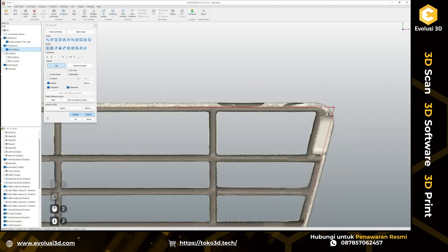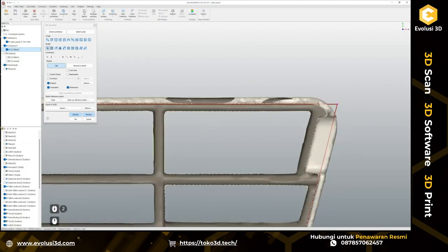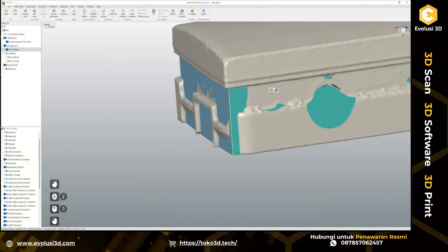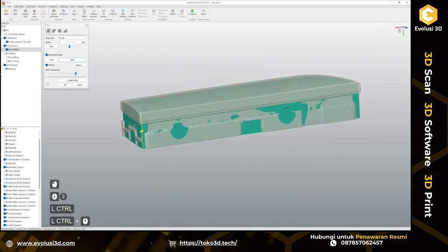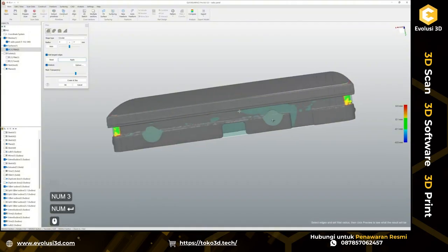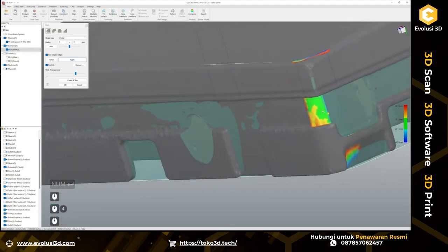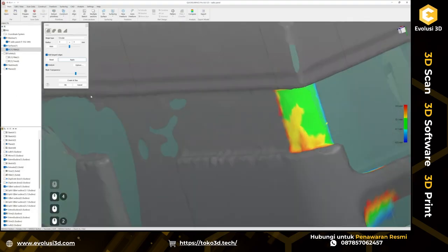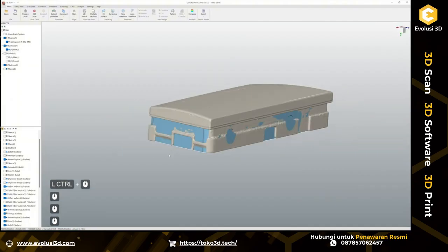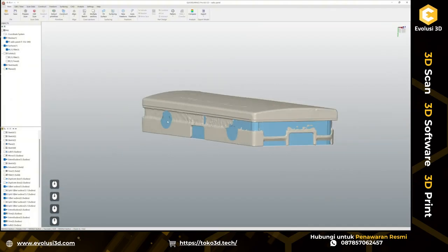Well, to be honest, since this corner is being cut away later, probably this might fit as a normal fillet as well. So let's try to add here a fillet, say 3 millimeters, same as on front side. Okay, this looks great. So easy way, no mess here.